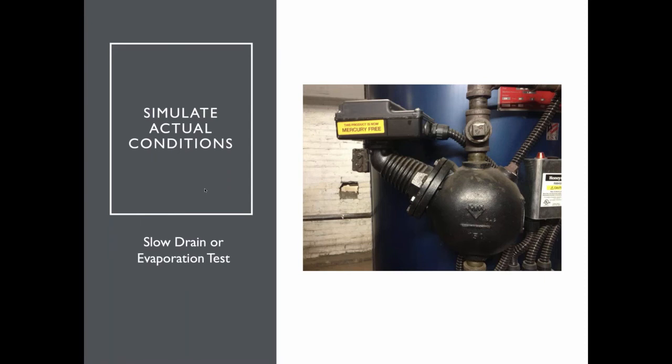This is becoming more and more requested on every job site: they want the evaporation test. A lot of these insurance companies, if we were going on to a steam boiler job, we would open up that valve beneath our 150 here, and we would document that it shuts off the boiler. Well, that doesn't actually simulate an actual condition, because you could have some junk in there that is holding up the float, if this thing has a float.